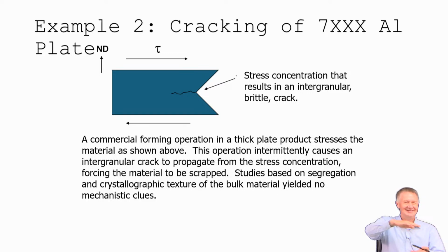So whatever that is in centimeters, right? 200. And then you want to improve the fatigue resistance, so you put a mandrel inside and you open it up, right? So you put it inside that hole and you just squeeze it out, and it hardens the inside of the hole, right? It's like a shot peening procedure or something like that. Sometimes they're starting to maybe use cavitation peening for this process, but it's a process that once in a while they'll have the wing spar completely machined out.